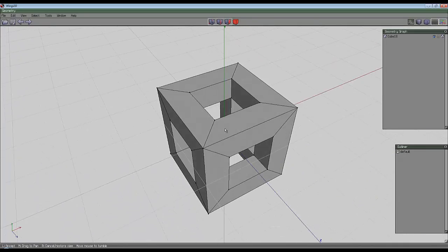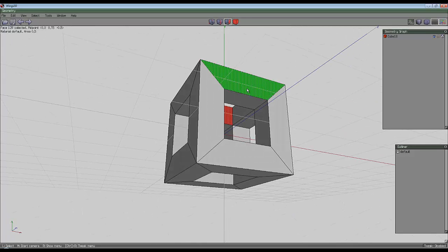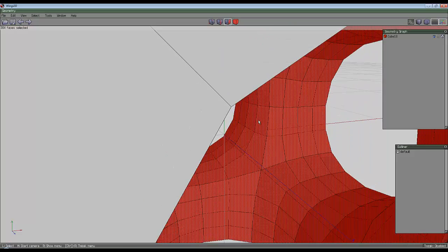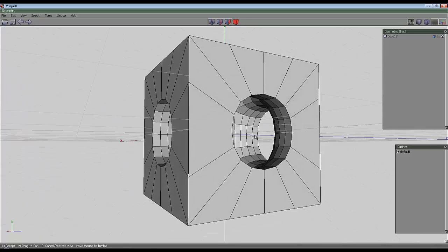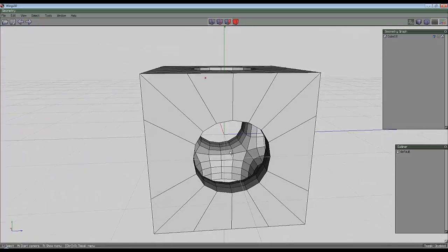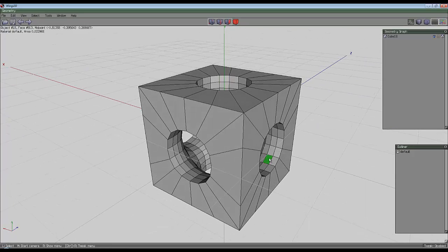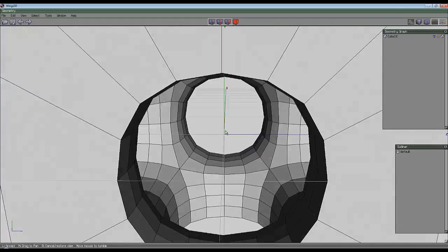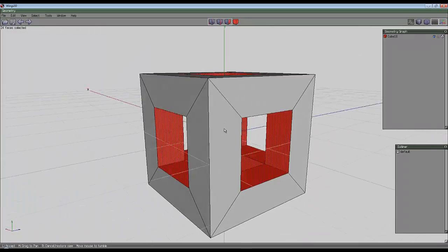So what happens, let's imagine, if we start to deal with this internal geometry through smoothing, so I hit the S key for smoothing, you can see we've got a nice transition on the inside here, and a circle, or close to a circle, actually it's not quite circular, on the outside. So I see this as another potential solution to the issue, if we can sort out the external geometry, because the internal geometry will sort itself out as it's smoothed. So here's another way of doing things.